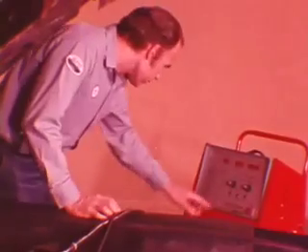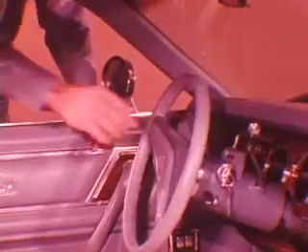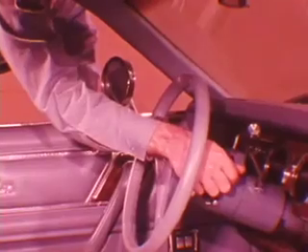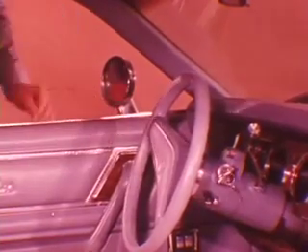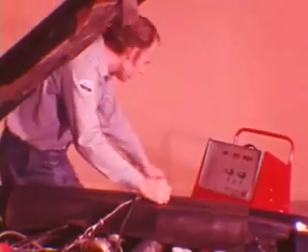First, press the start switch. Instruction code 1 will appear, which directs you to do either the RPM timing check or the diagnostic test. You begin the RPM and timing test by starting the engine and pressing the continue switch. However, if you have an engine that won't start, turn off the ignition and go right to the diagnostic test.